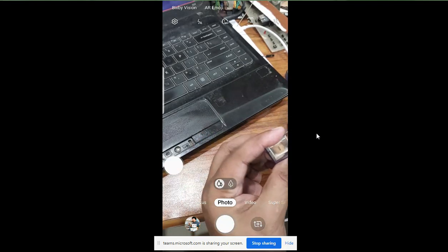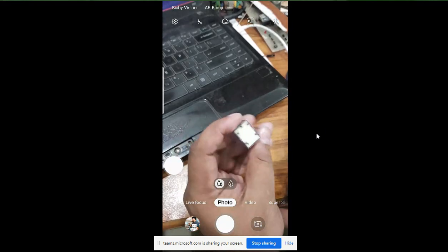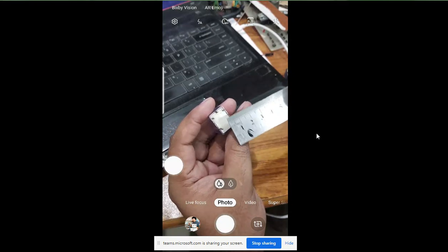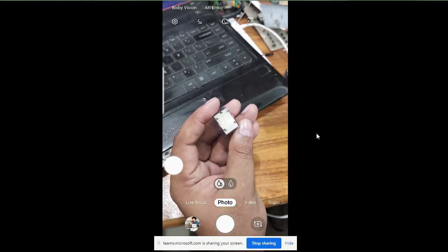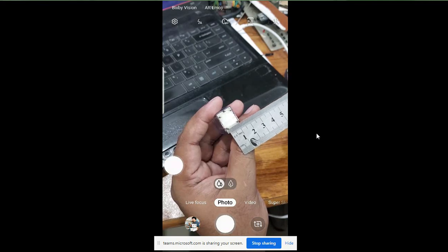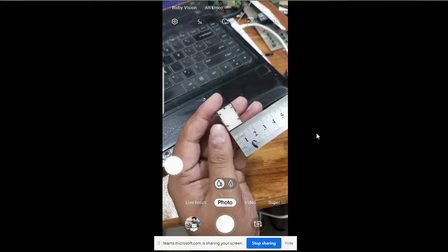Now if I want to find out the pins over there, these pins are very, very important. How am I going to verify this one? One very important thing: whenever you are going to place the pads on the PCB file or the footprint file, you will require the center to center distance. This is very important. So from the center of this pin to the center of this pin, you need to find out. And certainly when I know this distance, this is 16 mm.